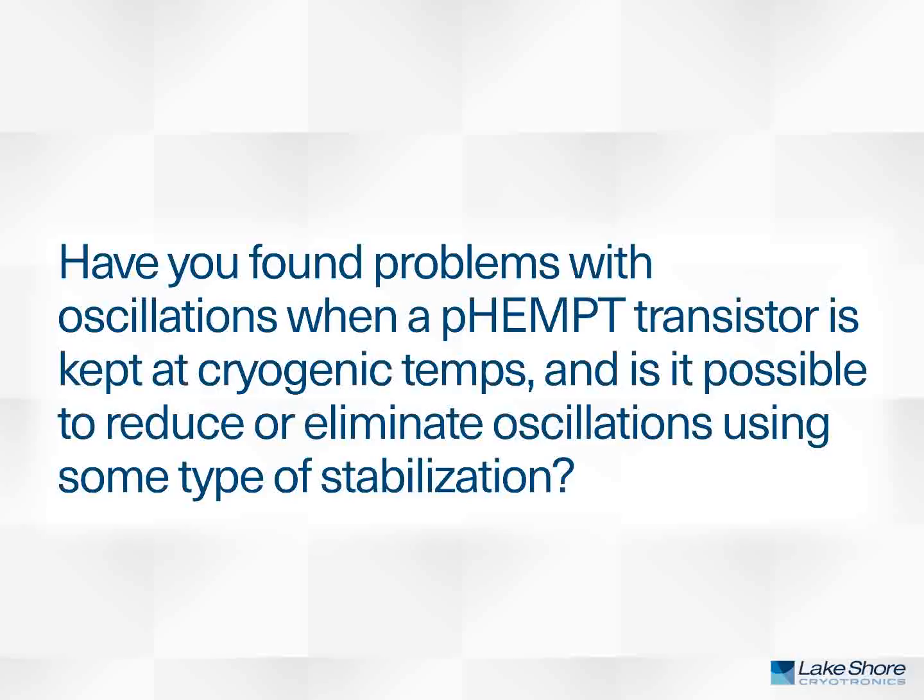What we ended up doing in this case was just lower the drain source current, or the drain source voltage, as well as some of the gating options. I think the takeaway there is that your electrical parameter space is going to change as you cool the device down, because the device fundamentally from a physical and materials standpoint is changing.